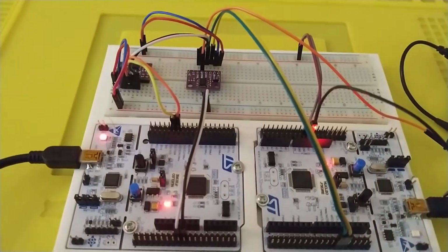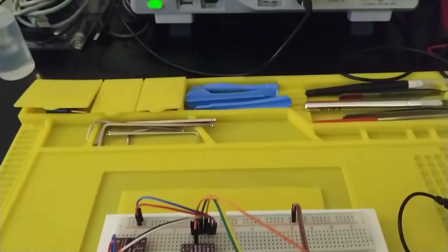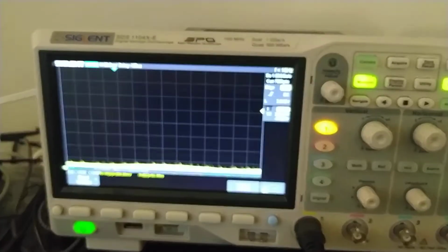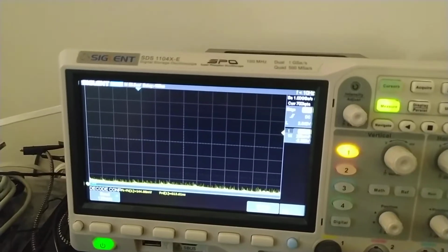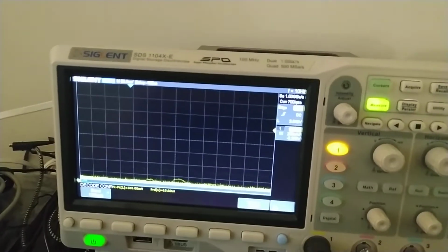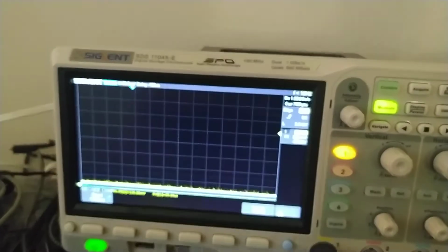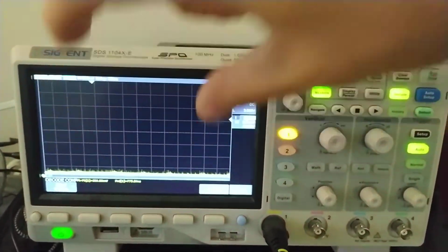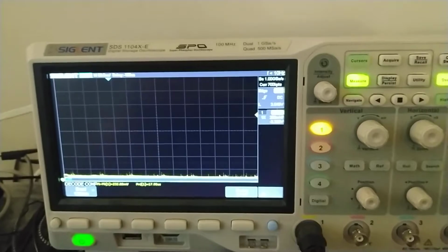Let's start off with the bit rate. What is the horizontal time scale that we should be looking at? If we have about 8 microseconds per bit, about 50 microseconds per frame should be enough to see an entire CAN frame within view.